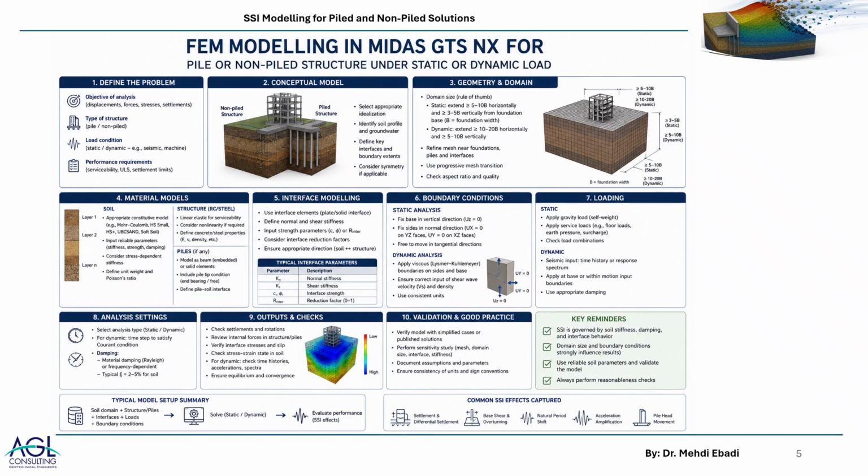We'll discuss that later, but as a high level comment, I would say don't use this for every interface between a structure and the soil. It looks nice, but sometimes the results that you get are not that realistic. It depends on the method of construction. That's a general note. So then we go to boundary conditions.